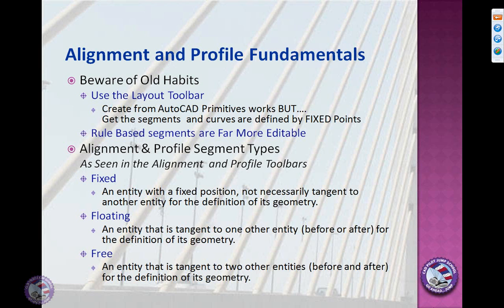And finally, we have free, which really means that it only exists to connect the pieces on the other sides, in terms of vertical curves. And this is a classic way that, hey, I want to always maintain this kind of vertical curve to both tangents. And that would be a typical design constraint that you see. Most people want to see that happen, and most of the time that's what we want to see.